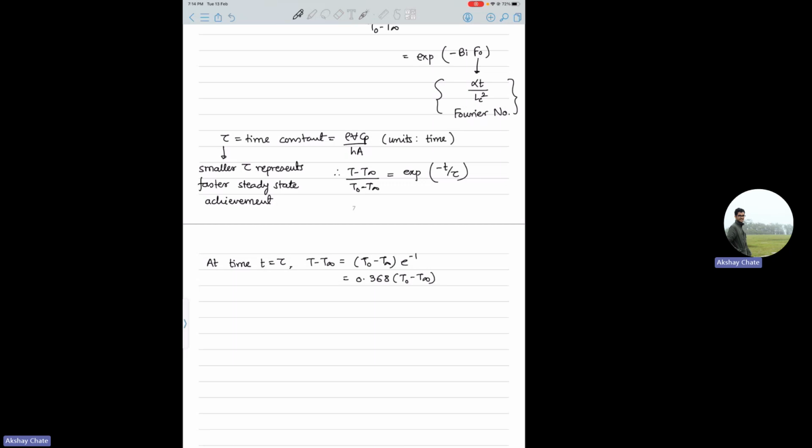So now we'll take some problems. The second application is quenching. You have a very hot metal ball, in quenching or annealing or any heat treatment process where you increase the temperature and suddenly quench it by putting it in a cold bath. There also, typically the Biot number comes out to be less than 1, and people typically use lumped capacitance analysis. We can take one problem from each, but you should know that these two cases are where these things are important.